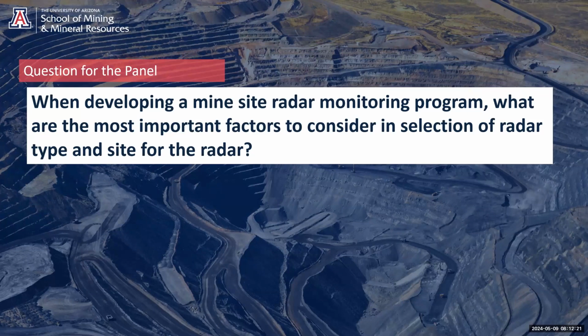Okay, well, thanks for the question. There are many things to consider. The basic one is visibility. How many radar systems will you need to cover the entire shape of your mine? That's the first thing. Secondly, the type of coverage that you have on the surface. Is it rock? Is it loose materials? Is it vegetation? Do you have water in the pit, like big sumps at the bottom of the mine that would cause some degree of problems?